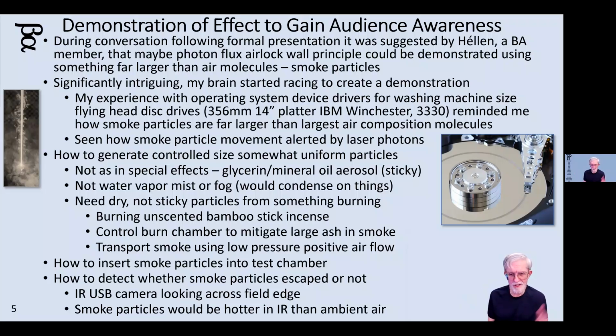And if ever the chamber, because there's a closed cover and you could take the platters out, if ever the chamber had anybody blow smoke in it, it would destroy the disk drive, because the smoke particles were larger by I think an order of 10, bigger than the gap between the head and the height it flew above the surface of the metal platters, so it would cause a head crash. So I knew, okay, smoke particles are fairly large. Maybe I can use them.